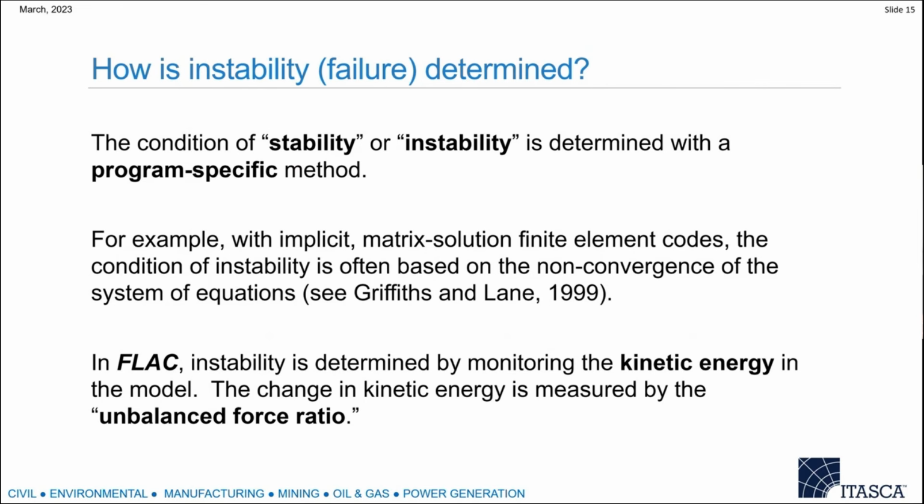For example, in finite element, calculations are usually based on an implicit matrix solution, and the condition of instability is often based on the non-convergence of the system of equations. But in FLAC, instability is determined by monitoring the kinetic energy in the model, and this is measured by the unbalanced force ratio.